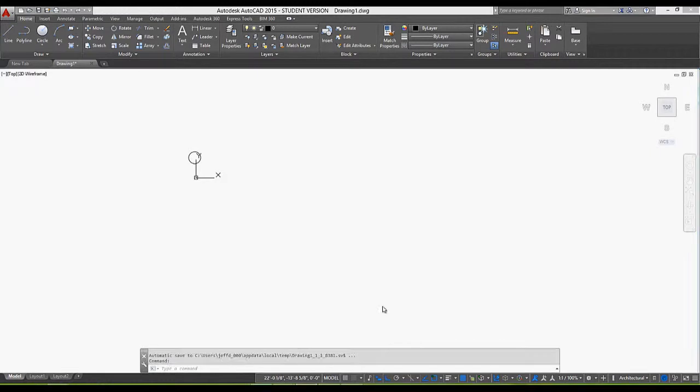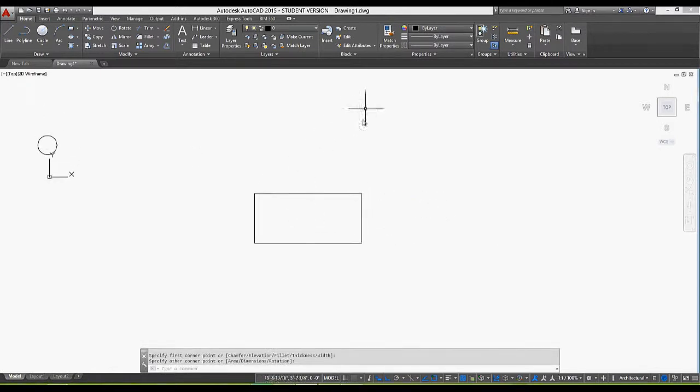Another way that we can use the object snaps is if we want to start to build upon objects. So first of all, if I take a rectangle and draw it, maybe I want to have a line that snaps to this rectangle somewhere. So what the object snaps are good for is that they can constrain that snap to that point on the rectangle. So for example, I took a line here, and if you have the snaps also on, you can actually override the ortho.